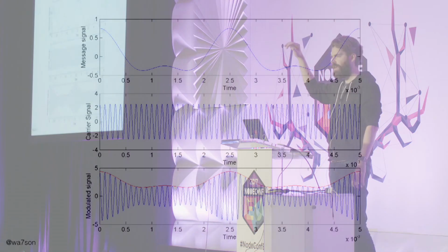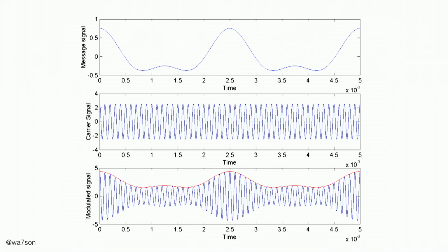And we could technically take that wave and plug it directly into the antenna, but the issue is that we would need to have a really, really big antenna, because the slower the frequency, the larger the antenna we need. And it would be totally impractical to send and receive waves at that speed. So we need to speed it up very, very fast to get it into smaller antennas. And so the way AM goes about doing this is that you take the very slow-moving wave that you see on top, and then there is what's called a carrier wave, which is the frequency you're tuning to on your radio. And it takes the shape of the slow-moving wave.